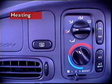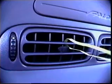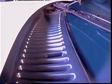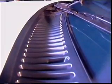This section examines vehicle heating and ventilation systems. To improve driver and passenger safety, a supply of fresh air is necessary to reduce fatigue and maintain comfort. Fresh air is drawn from outside, usually through ducts at the base of the windscreen, and directed to the passenger compartment. The air is then delivered through ducts and flaps, which are positioned to direct air to particular points inside the passenger compartment.